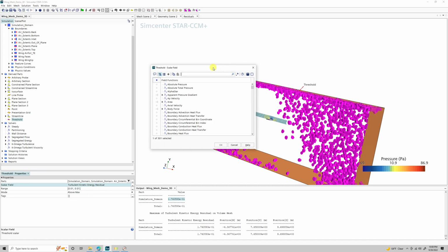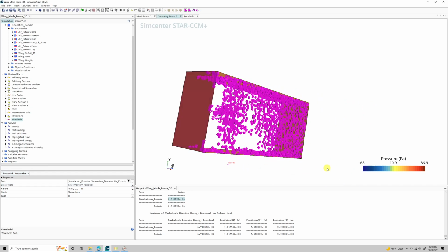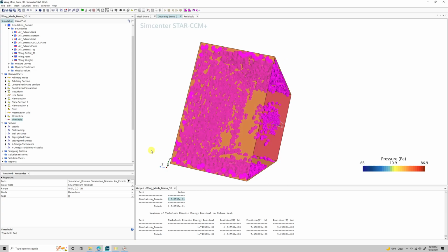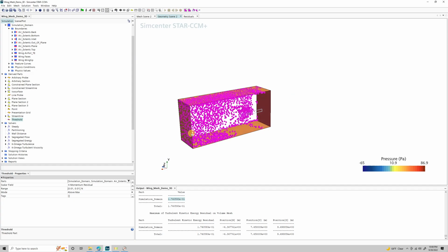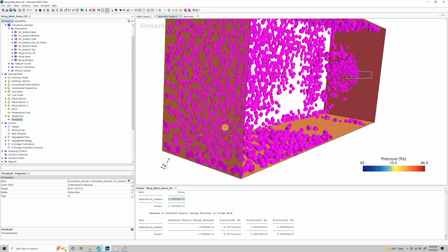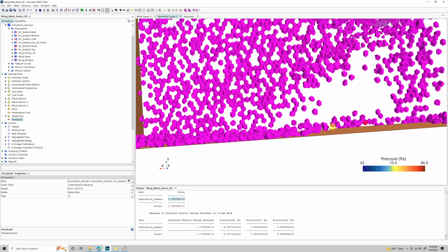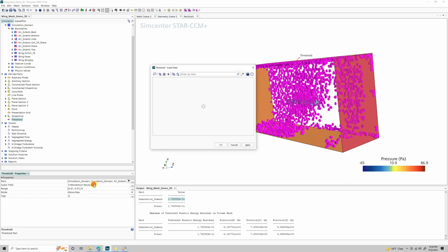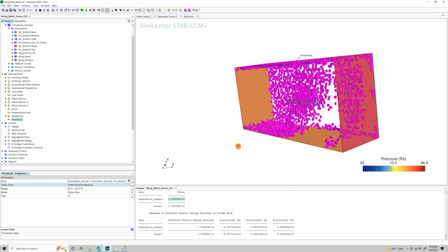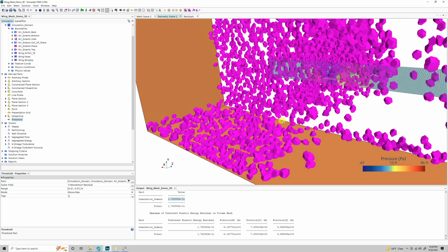etc. Let's look at X momentum instead. Well, if there is a problem with the simulation, this would pretty strongly imply it's because our cells are getting a little bit big towards the outside. Again, not that there necessarily is a problem with this simulation, just that we could use these tools, these threshold parts, and these residuals to find out where that problem is likely located. Debugging.